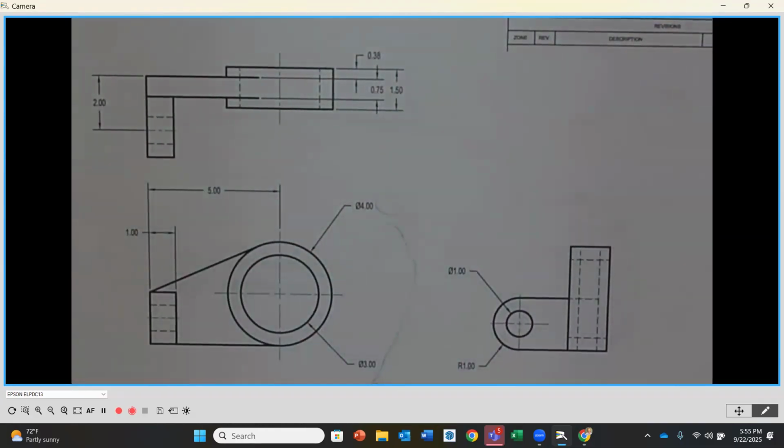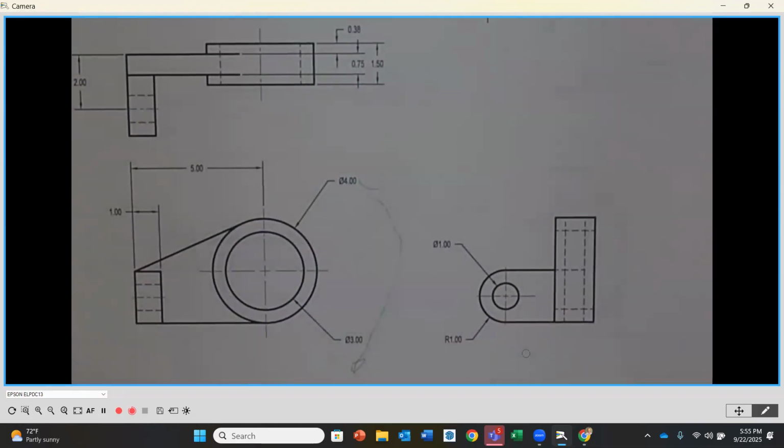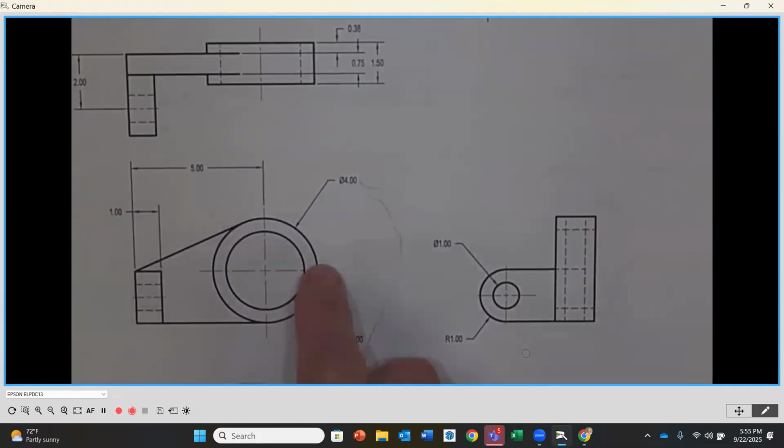You also are then going to be, when you're out in the industry, thinking about, how are we going to make this? And then the other thing is, and I know I'm kind of getting off track, but this all is related: what can you do in-house as opposed to having to send it out? It's always cheaper to keep things in your building and make them there if you have those capabilities. So as a designer, you want to think, can I run this across our milling machine that we have right here? Or do I need 5 decimal places? I have to send it out to be ground or reamed or whatever it might be.